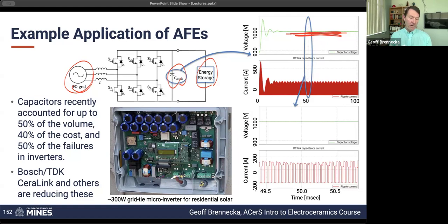You'll notice that, at least at the time when this inverter was made, maybe 10 years ago, 8 years ago, capacitors made up about half of the volume, almost half of the cost, and half of the failures in these kinds of inverters. It's a little bit better now, but it's still much greater volume, cost, and failure rate than we really want it to be. So this is an area where there's a lot of need for improvement in these capacitors.